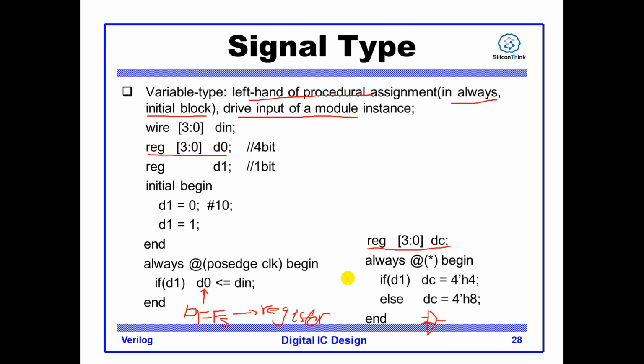So don't be confused with the keyword reg in Verilog. The keyword reg doesn't mean the signal will be synthesized to a register. It can be synthesized to combinational logic.